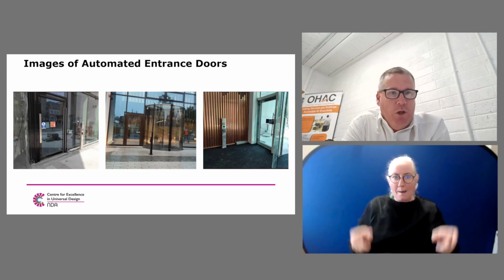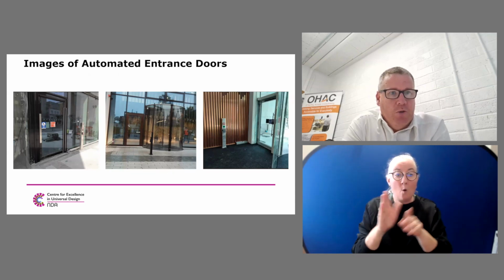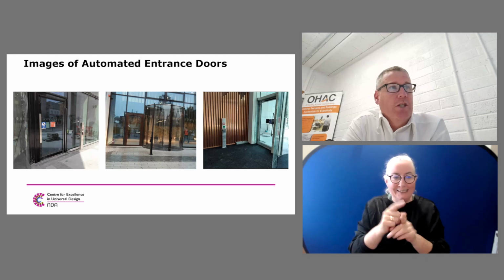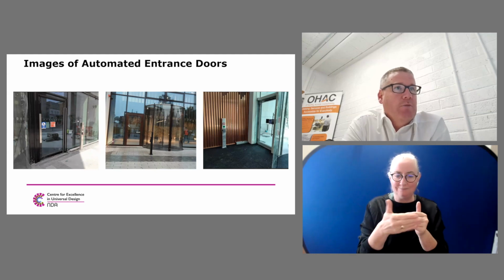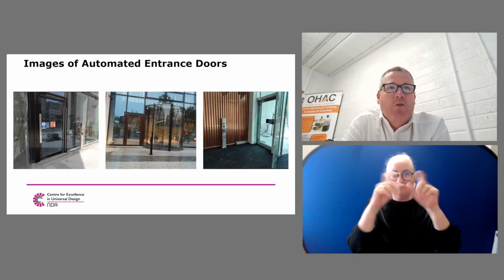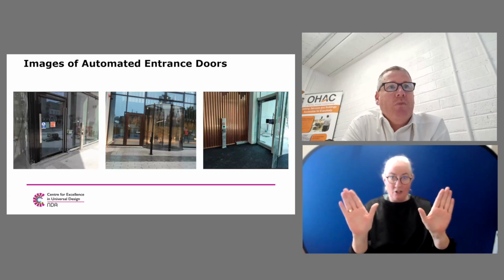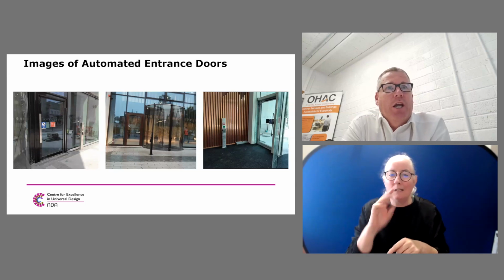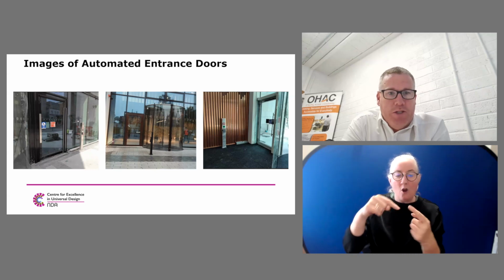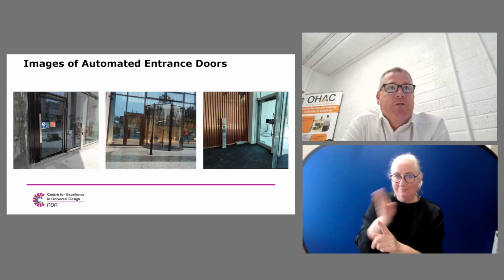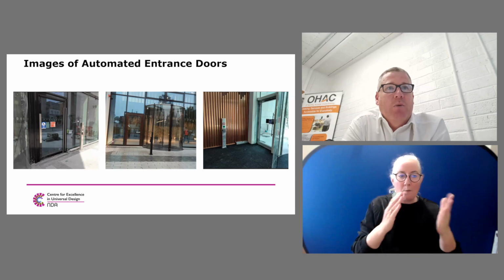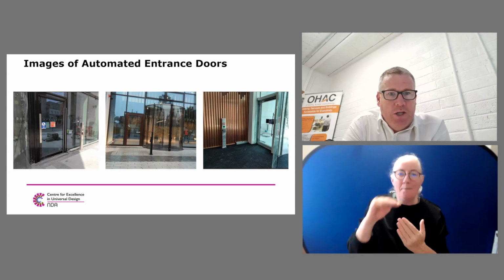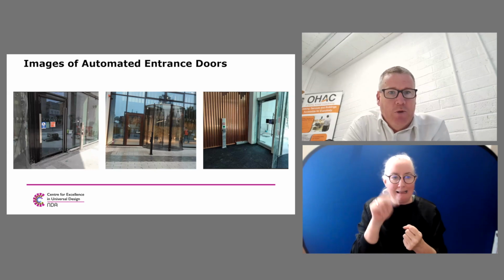You also have, when you have automated or power assisted doors, you need to put a symbol on the doors to indicate that the door is power assisted or automated. And again, you need to make sure that your glazed manifestations are designed. So if you can see the image in the center, again, it's a revolving door with a complementary accessible door, and the framing of the glass is thicker than the actual glass facade. So that will assist people with visual impairments to navigate and find where the door is.